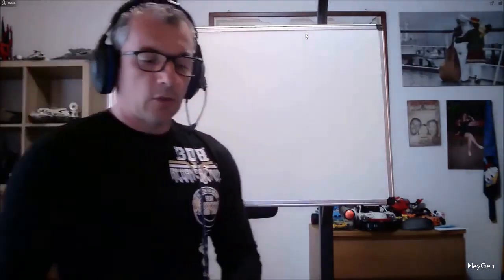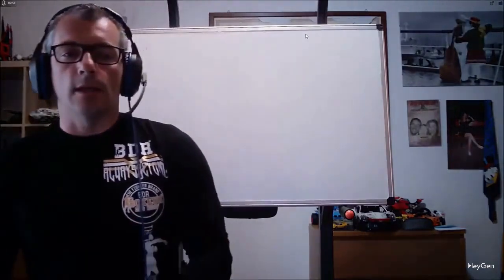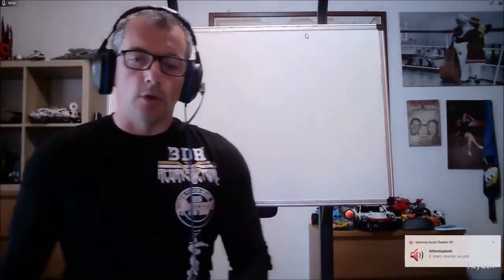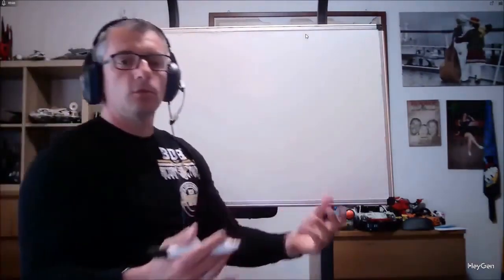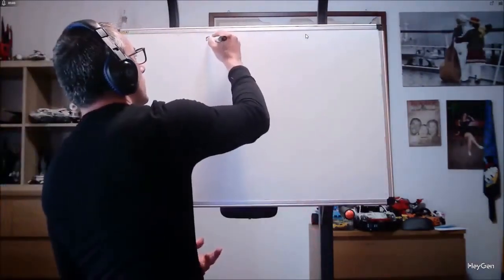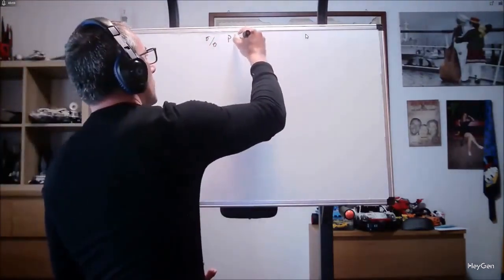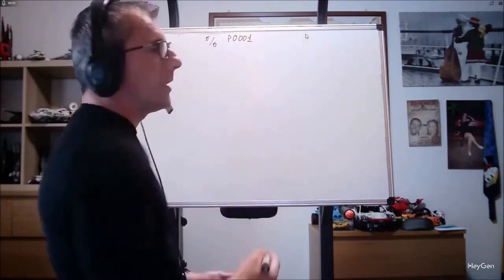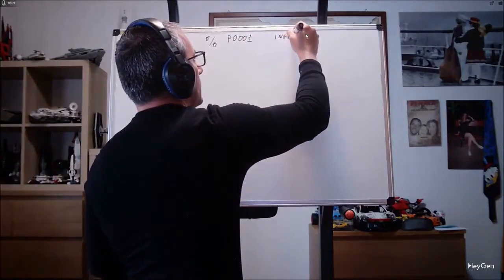So I was unsure whether to start with the movement of the axes or the preparatory functions. Basically, there is no rule. Let's start thinking about what the preparatory functions are, that is, what you tell a machine at the beginning of the program. At the beginning of the program, most lathes, but not all, need a special character. Let's say it can be a percentage sign, usually followed by the name of the program. So it could be P1001 in older lathes. In newer lathes, it can actually be a word like gear.